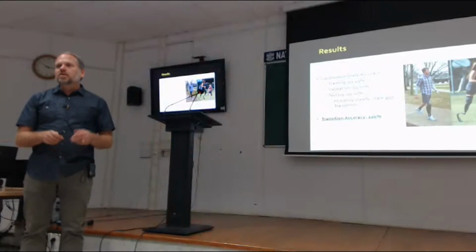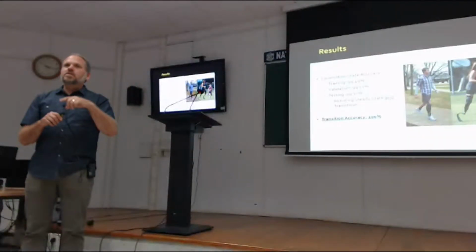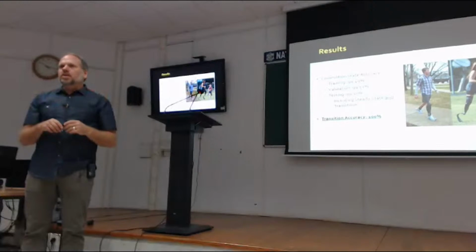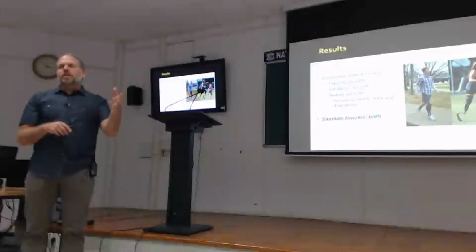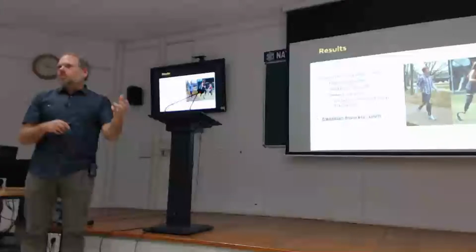So this allows us to build a little more of a weighting function into our approach, to say the heuristics predict that you're about to make a transition. That's more important than even knowing what the speed of your transition is going to be. It's more important to know that the current state of walk is going to change and just be ready for the next thing. And if we know the next thing is likely to be a run, with another layer of that heuristic level, then we can say you likely need this stiffness, because the first step of every running event has this required stiffness to be able to propel.